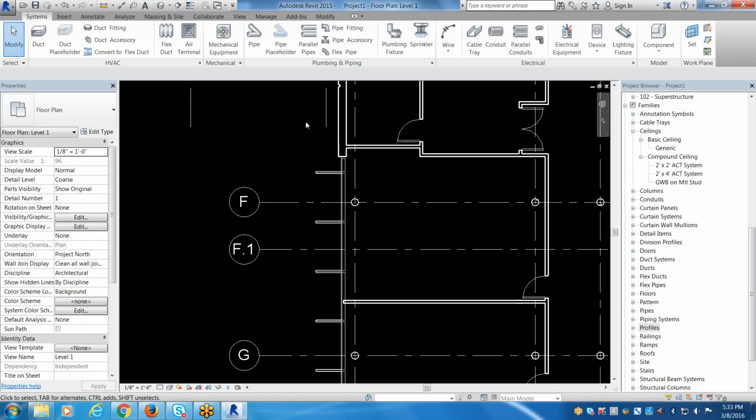It's a one-time deal. So let's say you're working on a 16 project, and an engineer comes to you and says, oh, we don't have this in our template, but I need this specific VAV type or this specific pipe fitting, and we use it a lot. Don't create it in 16, even though that's where the project is. Open up 14 and create it there. Save it to our Revit 14 template family folder, and then copy it to the 16 project, right? So that we always have a good one out there for us to reuse. But in this case, let's just say we're in 15.